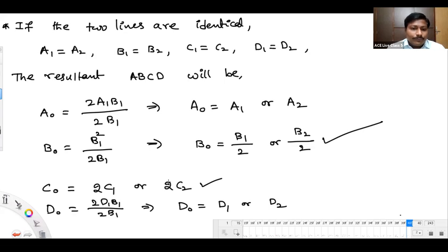Following all of you? As parameter B represents series impedance and C represents shunt admittance, if two identical lines are in parallel, B becomes half and C becomes double, but there is no change in parameters A and D. Okay, next thing. One more simple thing. Observe now.